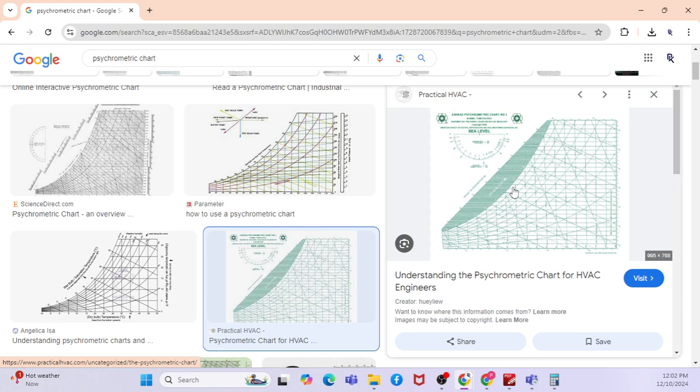If I get 1, then I will draw here 24, 50%, then draw a line. I will hit here, and that will be the supply temperature. Clear, right? When I say, for example, 0.9 or 0.8, then the line will be inclined. That inclined line will come and intersect here somewhere. Basically, that will be the off-coil temperature.